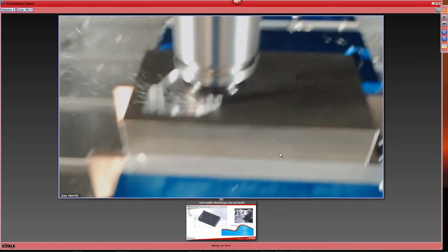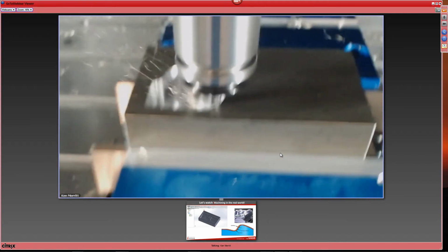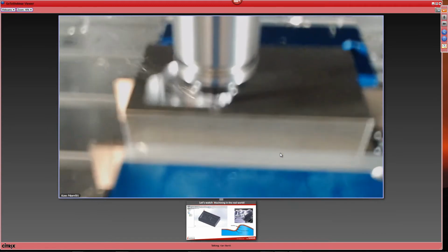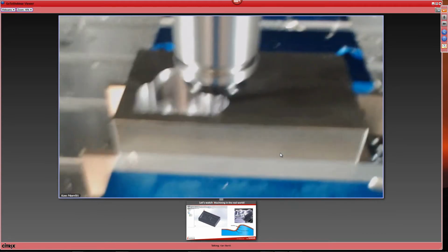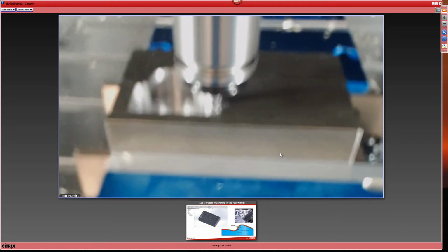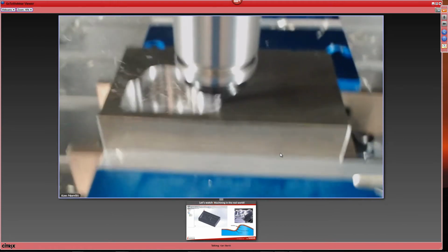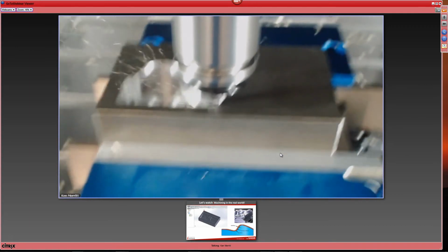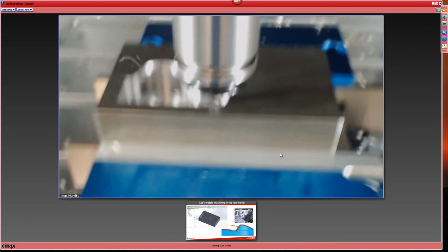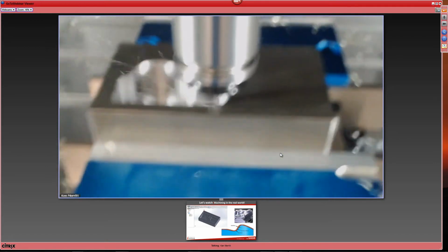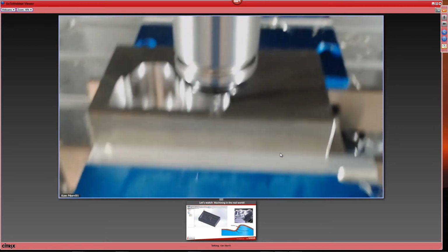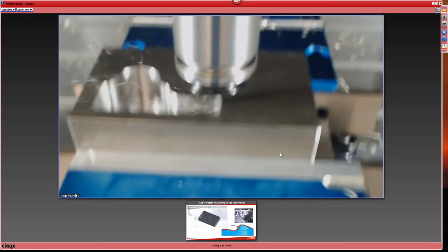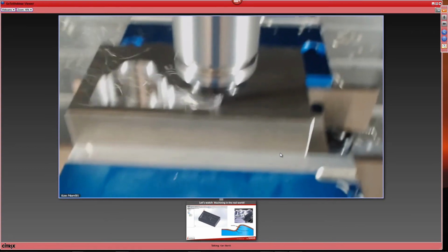One of the things that's very unique about iMachining is the fact that we are continuously updating the automatic stock remaining definition during the runtime of the algorithm. So at each movement of the tool, the algorithm knows where it is safe to move the tool with regard to the stock remaining. Okay? Now, what that does for us is we don't necessarily always have to come up to the rapid clearance plane to be able to reposition the tool.